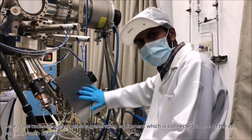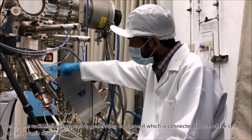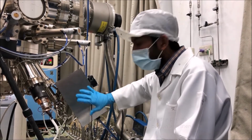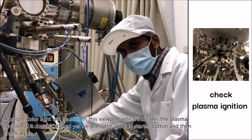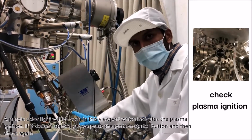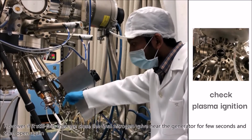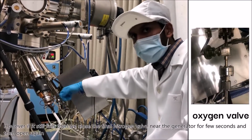Here is the radio frequency plasma generating equipment, which is connected to one of the cell ports of the growth chamber. Once we turn on the flow into the chamber, we can check the plasma ignition. A purple color light will be seen in this viewport, which indicates the plasma ignition. If it does not start yet, then we press the ignition starter button and then check again. However, if it still fails, then we close the final nitrogen valve for a few seconds and then open again.